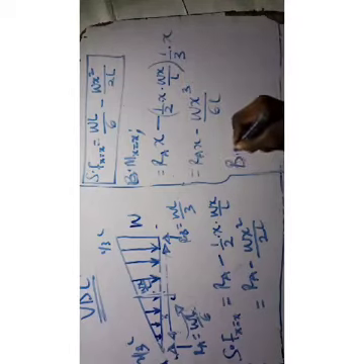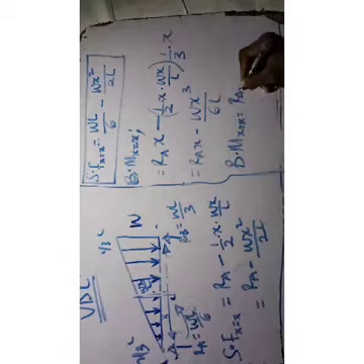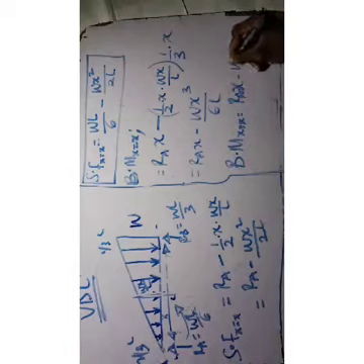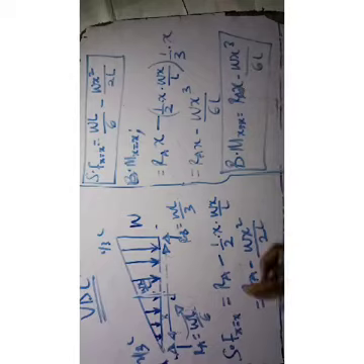So the bending moment at any section is equal to RAX minus WX cube over 6L. You can also cram that and jot it down. Very important, you note it down. And you can remember that your RAX is also WL over 3 times X, so you can simply substitute it.